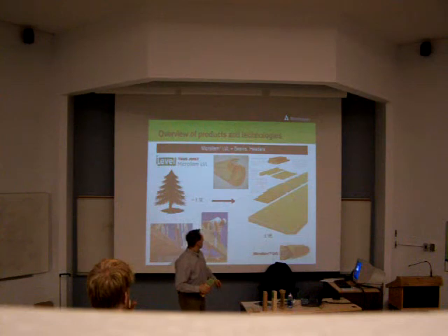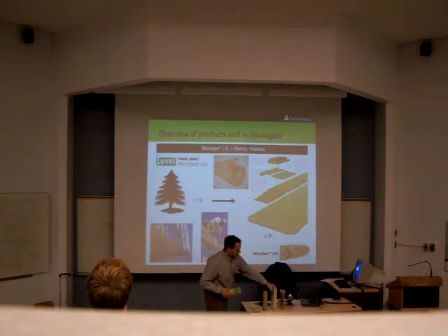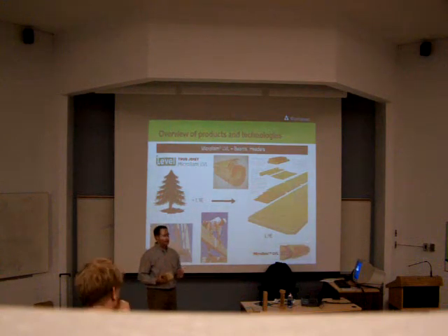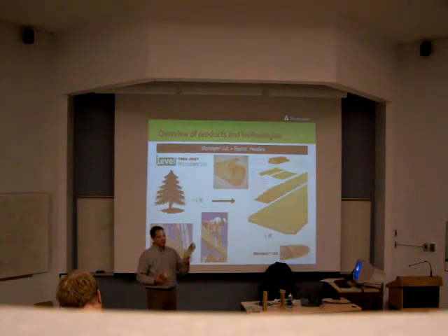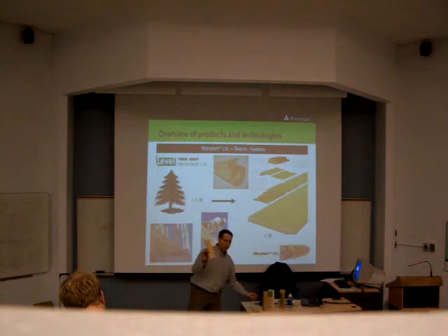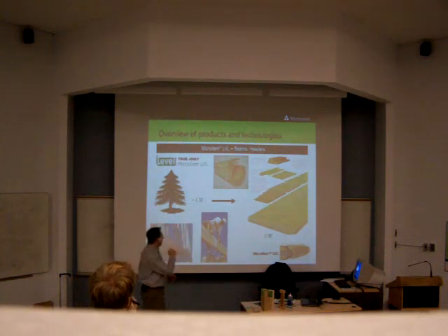Okay, so we make LVL in 1 3/4 thick. There is actually one manufacturer I know that makes it 3.5 inch thick. It's very rare. We don't really see it much in this market, but it can be done. Timber strand, to rewind here, all of the beams are made in multiples of 1 3/4. That's kind of the standard in the industry. So timber strand is made 1 3/4 and the solid billet of 3.5. So 2 times 1 3/4. Here we go into 2 ply. So that can be made in 3.5. We only make 1 3/4 of this, but the Parallam can be made thicker.